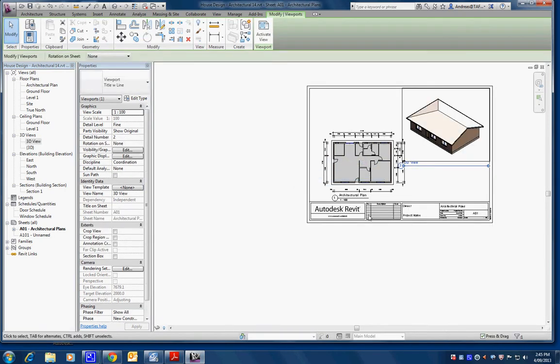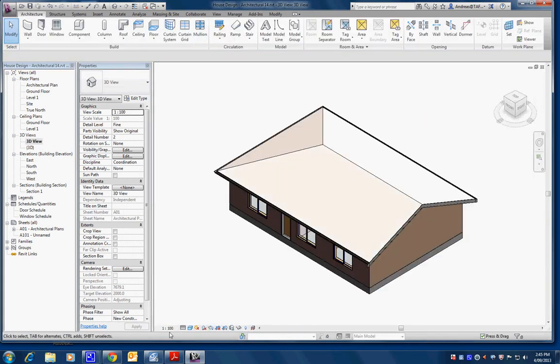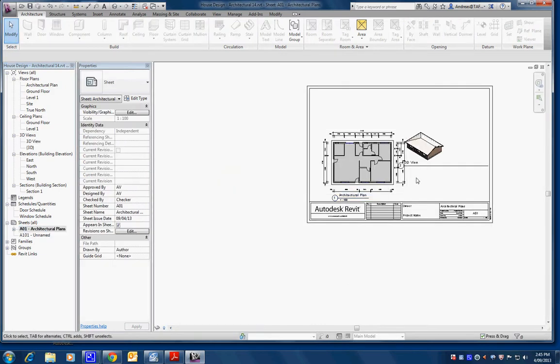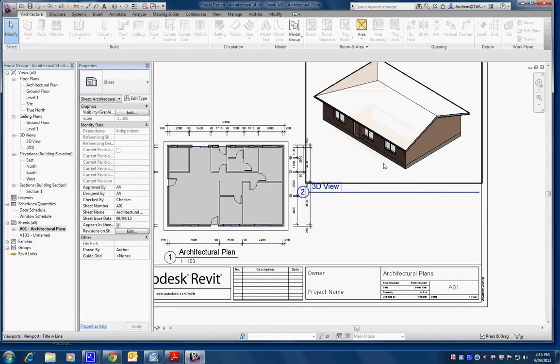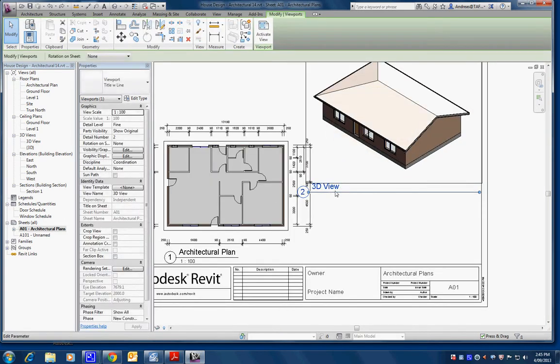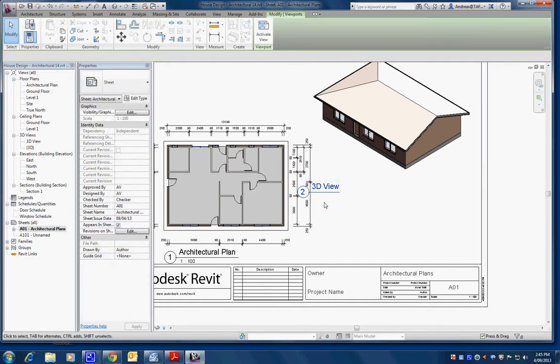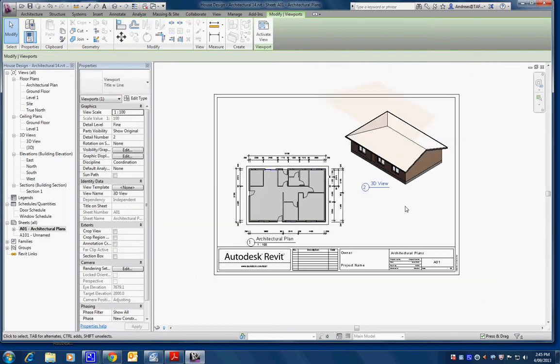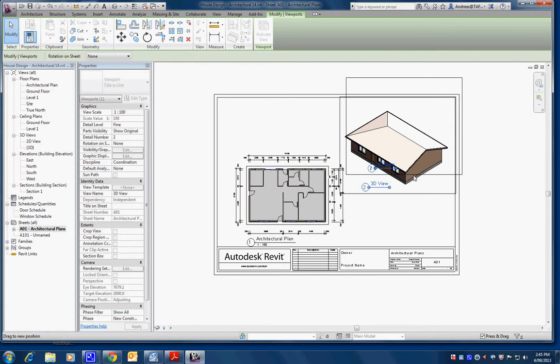That's not too bad. But if you want to get it a bit smaller, you can muck around with the scale as well. You can make the scale, say 1:200. And if I went to here, you find that it's a bit smaller now, a lot smaller. Right? Don't really want that. That's fine how it was. And you can again click on here, and you can change this, and then you can click on here, and you can move this, put it somewhere a bit more comfortable, and then you can move the whole thing by clicking on the viewport thing.